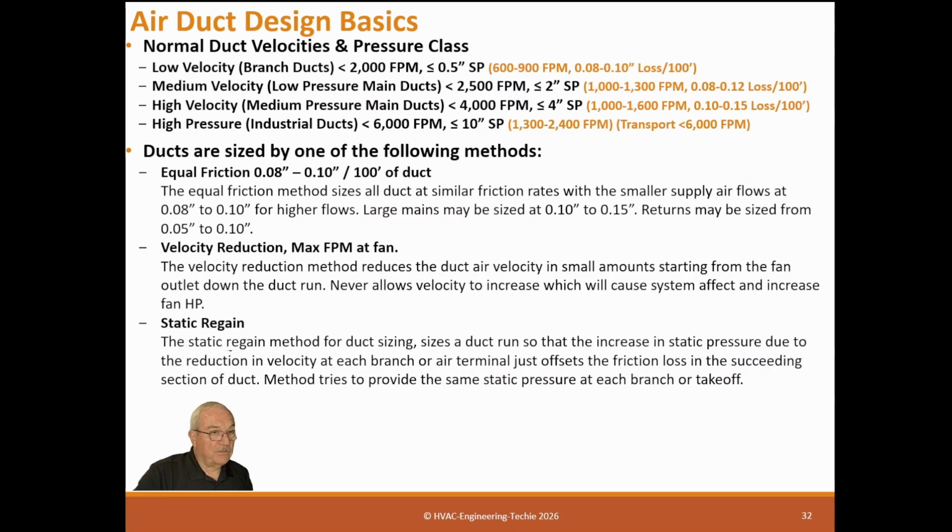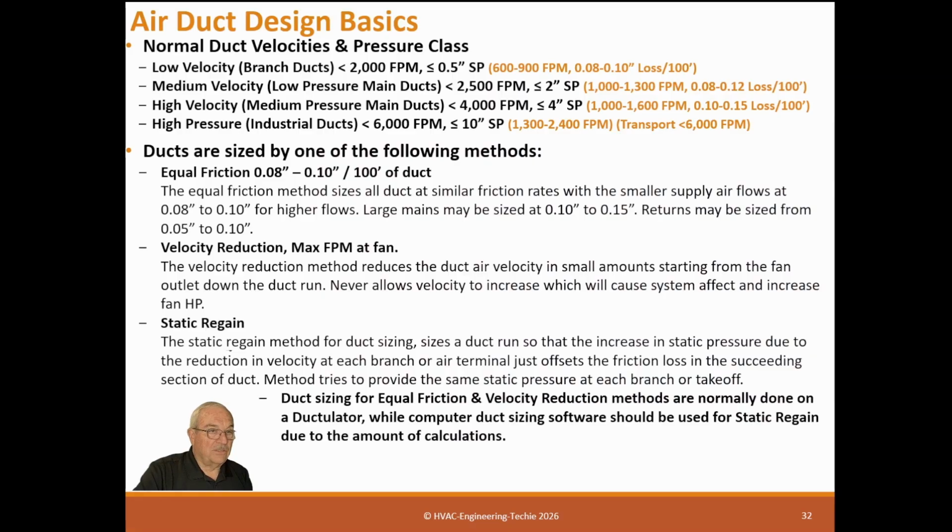You could do it nowadays with a computer program. It wouldn't take as long, but those are the three methods: equal friction, velocity reduction, or static regain. The way I do it nowadays is I use equal friction and velocity reduction kind of combined, but equal friction is really ruling the roost. For me, it's just easier.